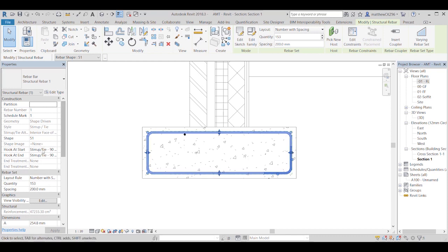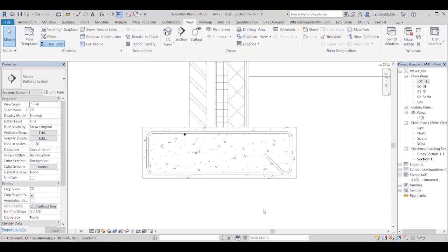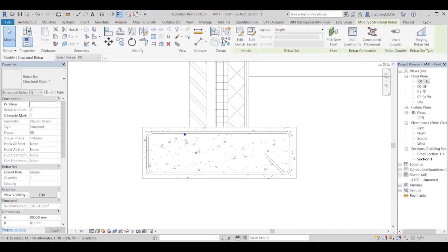Now the link always usually has a tick in the drawings I see. So let's go ahead and you can change that by here. So let's make the stirrup tie 135. There we are. You've got a little kick. That's just to indicate that it's a link. I think it's like a generic annotation to show people, yep, that's a link or an L bar or something like that. Okay. And this is our straight bar.